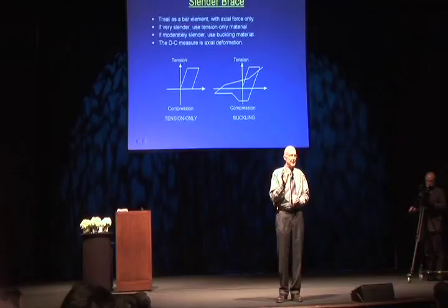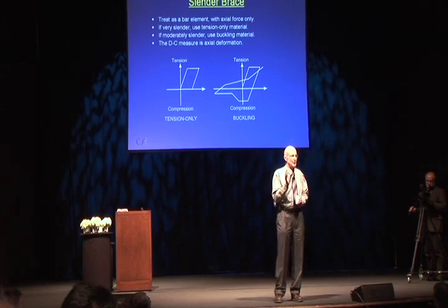That's okay. When you're using bending moment, you use the peak bending moment at the end of the beam as your demand capacity measure. If you extend that and say, well, I'll use the peak curvature right at the end of the beam, in that last millionth of an inch, that's not going to work.